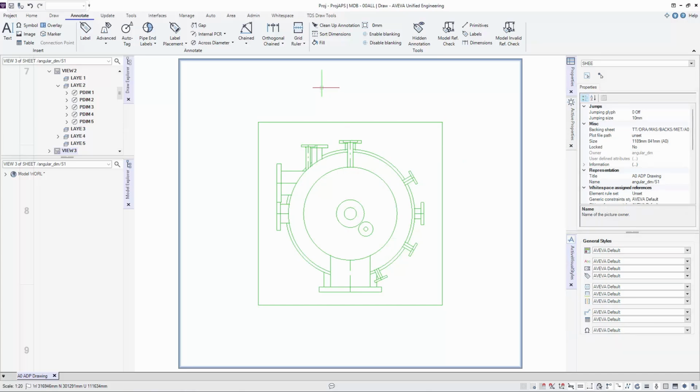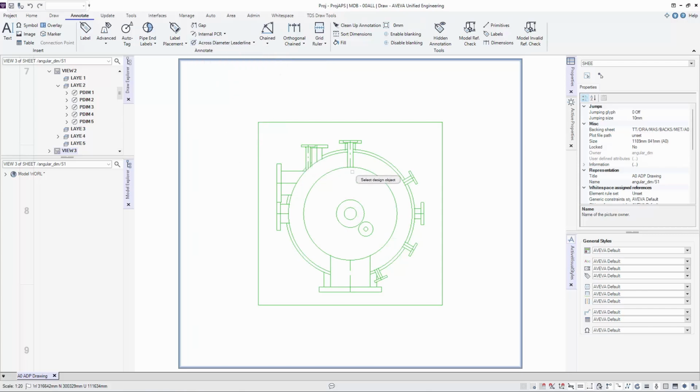We open the radial dimension pull-down menu, which lists several creation options. Similar to the pitch circle dimension, the list is divided into diameter and radius types, each offering different visual styles. We select one of the diameter options from the radial dimension menu. Unlike the pitch circle dimension, this command requires selecting a 3D element, and the value is derived from the element's properties. Not all elements are suitable. For example, a box cannot be selected, but a vertex of an extrusion element with a defined radius can be used. We create another radial dimension using the radius mode to display the radius value instead of the diameter.